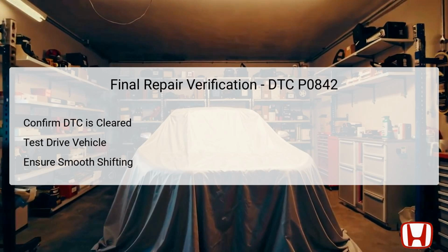After completing the necessary repairs, it's essential to verify that the DTC P0842 is no longer present. This is accomplished by utilizing the Honda Diagnostic System, HDS, once again to check if the trouble code has been cleared. Following this, a test drive is advisable to ensure that the vehicle performs as expected under real-world operating conditions.